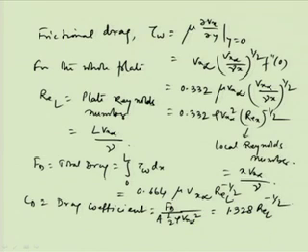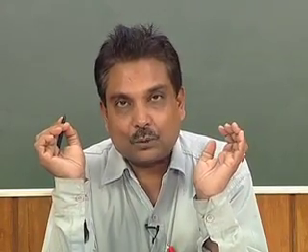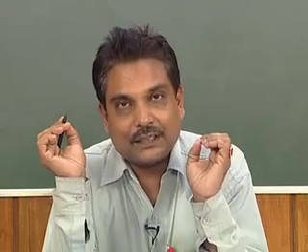And exactly similar analysis we have to do. We have got the expression for velocity, and now we have to find out the expression for h bar, or heat transfer coefficient, and we will be finding that in terms of Nusselt number. So, here we have found out the wall drag, or wall momentum transport: tau W is nothing but the momentum transport at the wall.